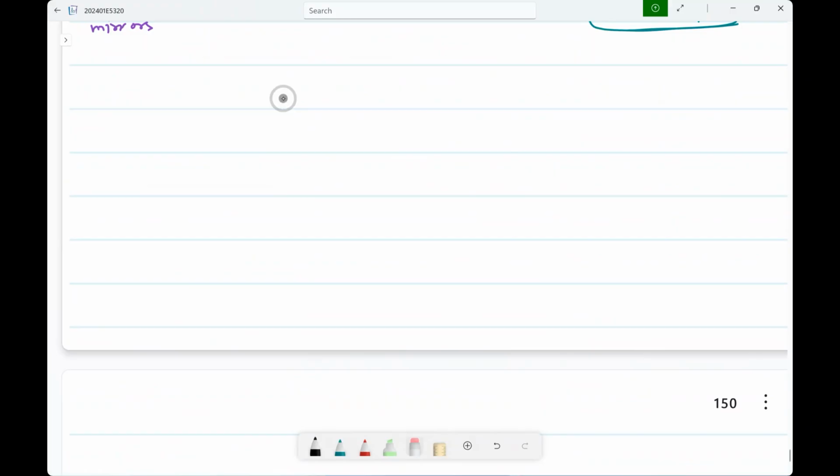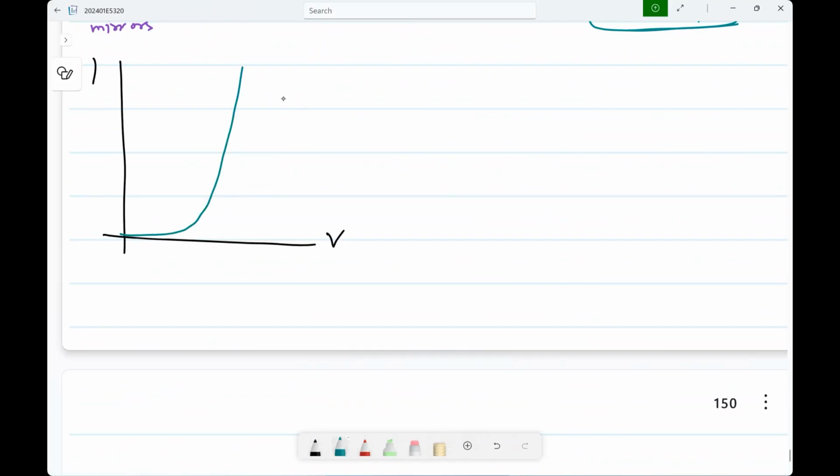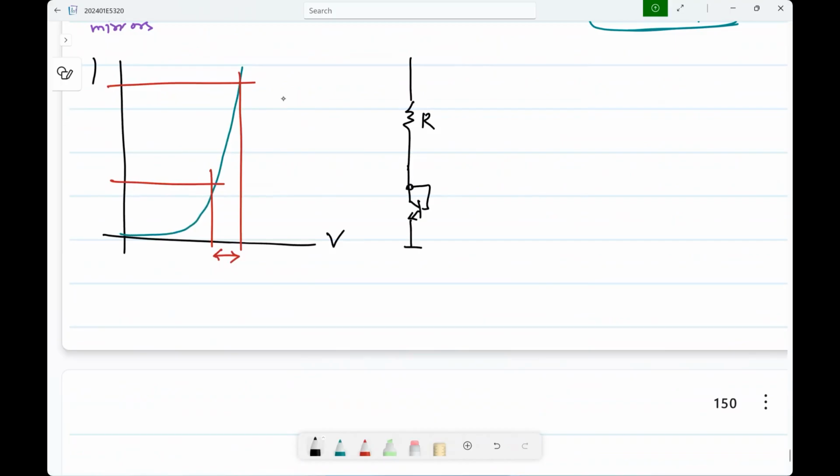Of course, it is not constant. The IV curve is an exponential, and because it's an exponential, you assume that in some reasonable range of currents, the voltage varies over a very narrow range. Now you can use that as a feature also. If I have a resistor and a diode, meaning a diode connected bipolar transistor, what should this voltage be? For analysis, you will just say 0.7. So potentially we can say, I have a constant 0.7 volts here. But the question is, how constant is it?